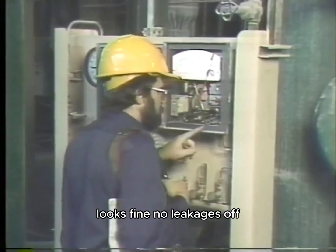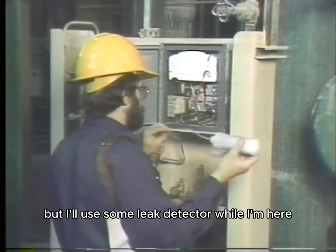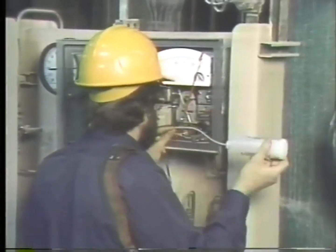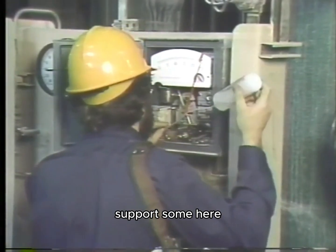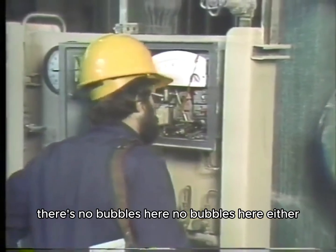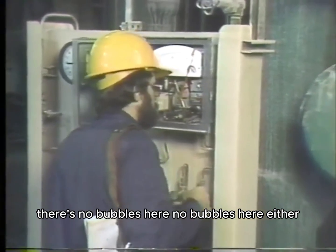Looks fine. No linkage is off. But I'll use some leak detector while I'm here, just in case there's a leak in one of these lines. Squirt some here, a little over there. There's no bubbles here, no bubbles here either.